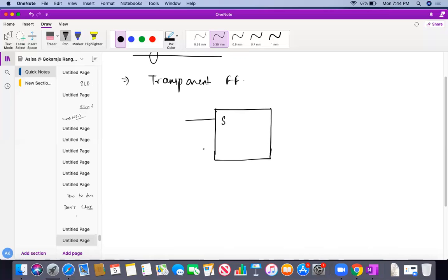We have already studied the SR flip-flop, which has a clock, Q and Q bar, and here this is my S. So how do we get the delay flip-flop? If I put a NAND gate over here, which will act like a NOT gate, this is my D flip-flop.